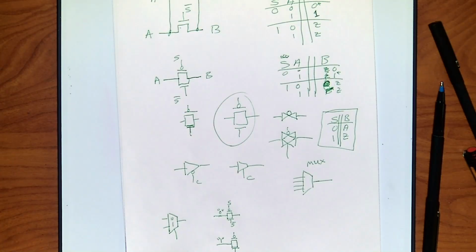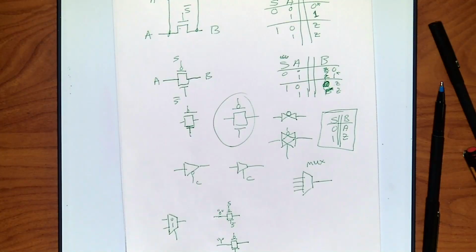All right. Now what do I have to hook to this so that a 1 opens it? I want the exact opposite. All right. Now notice kind of nicely these two are the same thing. So I can kind of hook them together. All right. And just hook that to S bar. Which, if we want to think about it, I can just draw my inverter this way, which means S going into the inverter. Fair?